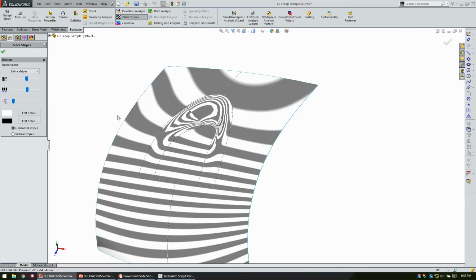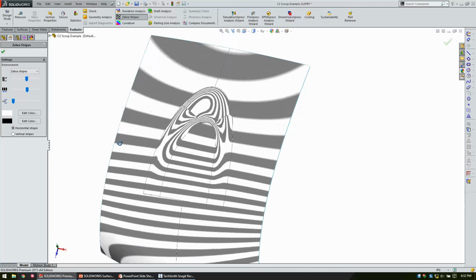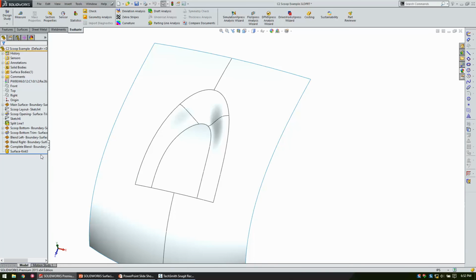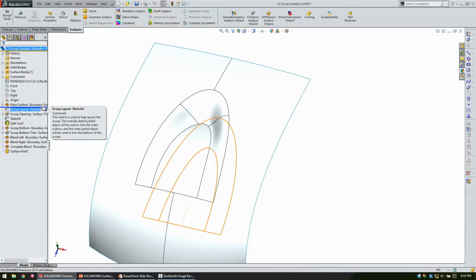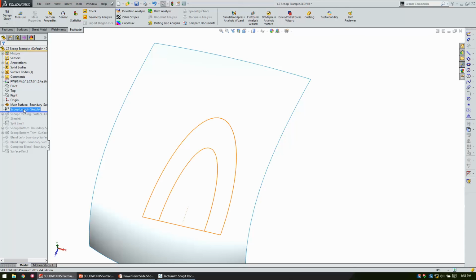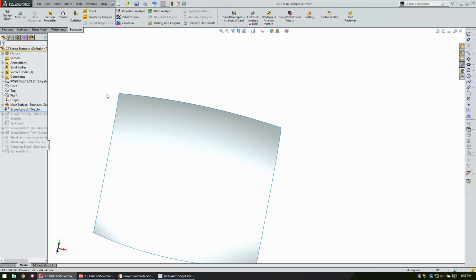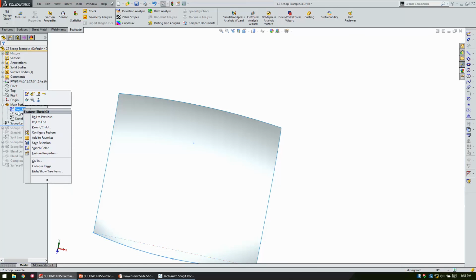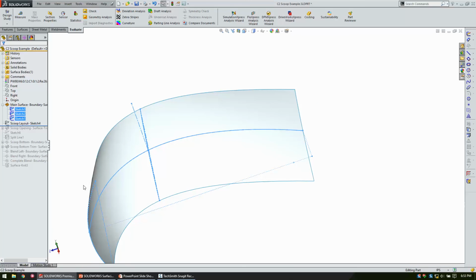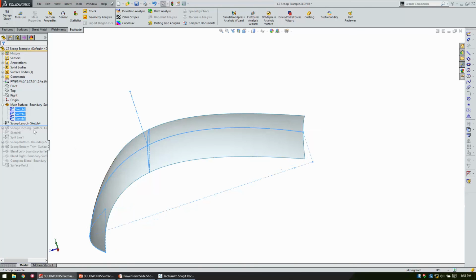But if we look at curvature, we can see how the transition here is extremely smooth. So this would be like automotive C2 or C3 surfacing. And the only way to really pull this off without using surfacing is, in 2015 or 16, I don't remember, they added in the fillet command conic rho and conic radius or something like that. But basically here's your main surface, which was again a boundary surface. So we had these 3 sketches because they changed, this is at a tighter radius than that here. So they changed the direction of it as it went.